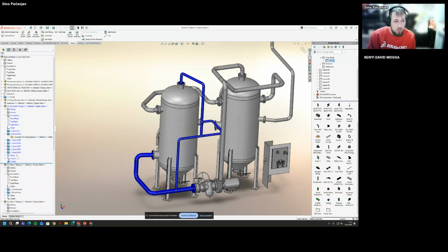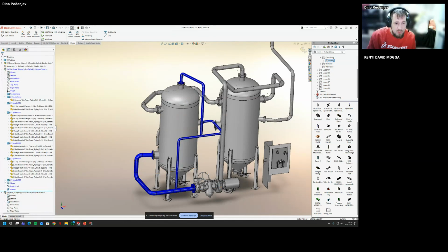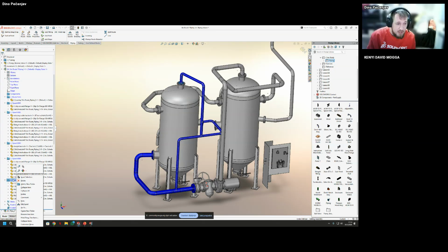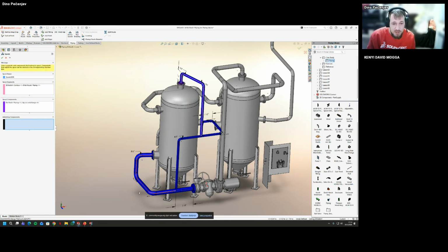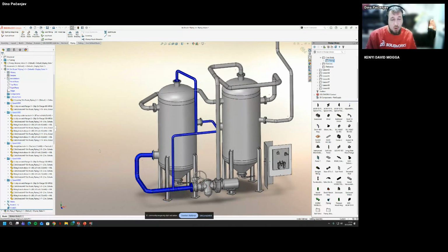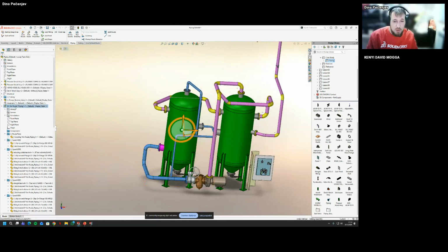So what do spools also do? It also changes the spools. We can use define spools. If I want to edit one, I can just click it, right click on the folder, edit spool, and say I don't want this part of my spool. I can edit it, and it also defines where everything is. So the spool in this subassembly is here. Also, the most important thing is when we're creating the drawing, so we're going to that bit.